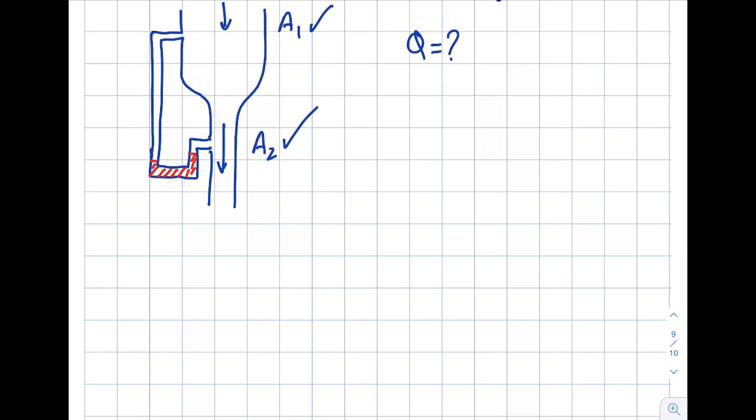Number one, the step is basically to determine the control volume. And I have received a few questions about this. You do not include the manometer into the control volume. The reason is that the manometer is a static pressure measuring device, so there is actually no flow going into this branch, okay? When you look at this branch, there's no flow over here. This is all stationary, and the control volume is for fluid dynamics, right? So for that reason, I'm not going to include that, okay?